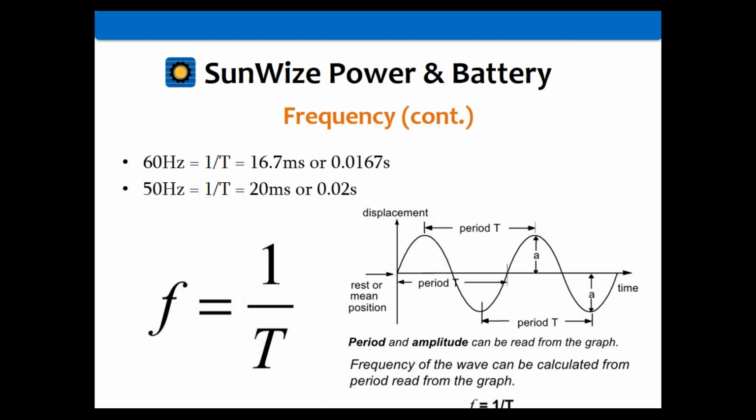If you have something in the 10 to 11 millisecond range, that's pretty quick. That's what we call less than a cycle. Most AC loads can handle a blip of less than a cycle without going offline. But if it takes as long as 50 milliseconds, that's about 4 or 5 or more cycles. That's probably going to knock your load off.